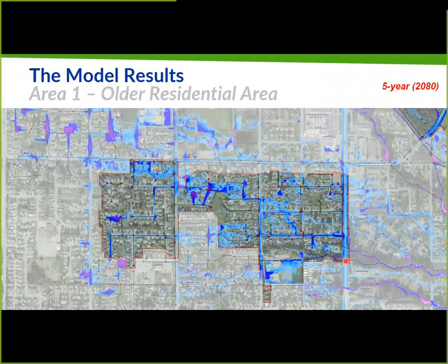So this really, I think, reinforces this whole idea of past development that really didn't consider overland flow paths and past water courses, where they went, and so on. So these water courses that were basically put into a pipe, they would flow overland, but that overland flow path doesn't follow a roadway. So in this case, there really is no safe overland flow path. And the consequences of that in terms of property damage are quite significant.